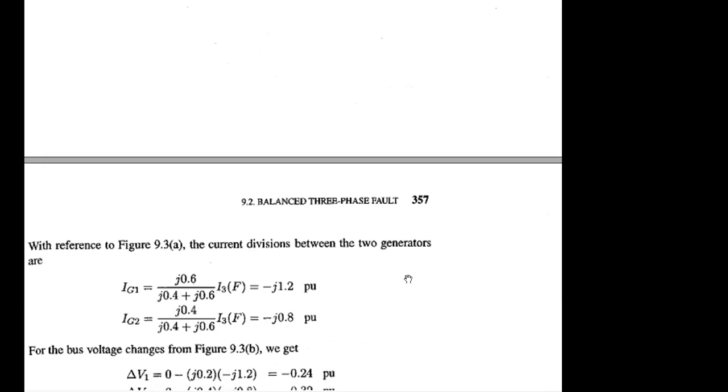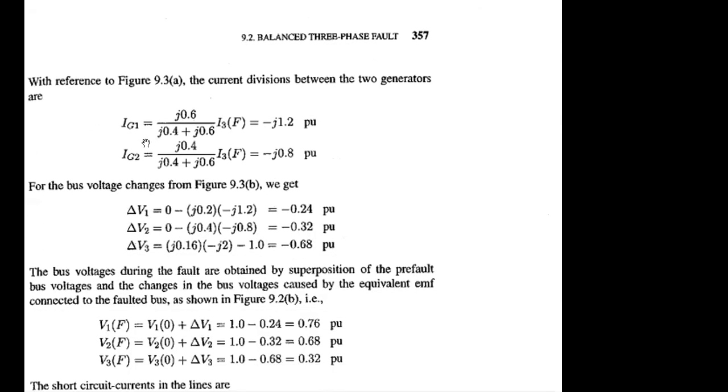When you have the generator 1 path, you can consider the voltage drop over that path considering the impedance attached to it. The drop over that path will be this current times the impedance of that path up to V1, which is 0.2. So we can find the drop over that path.